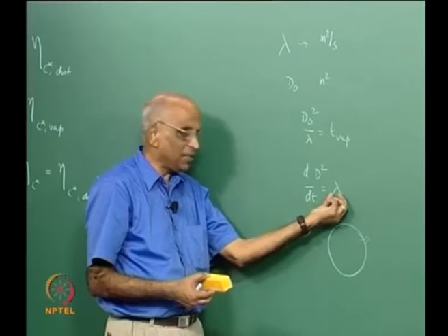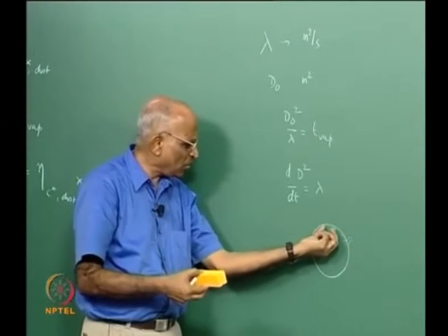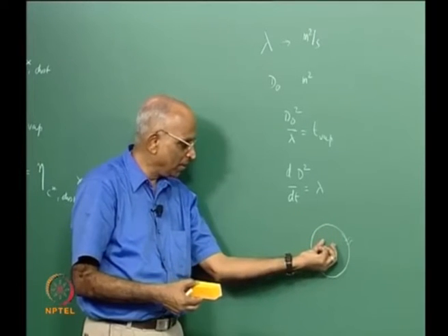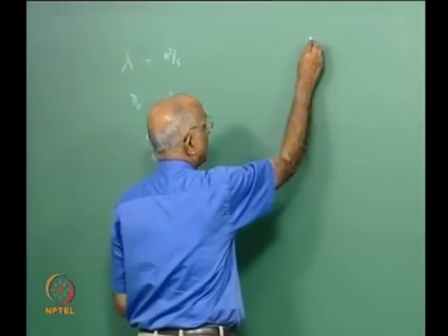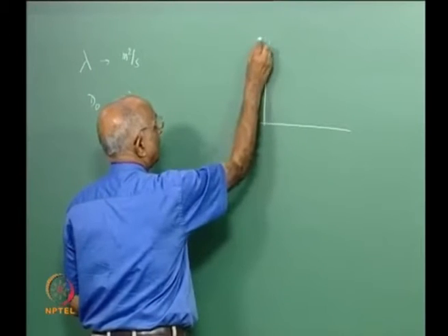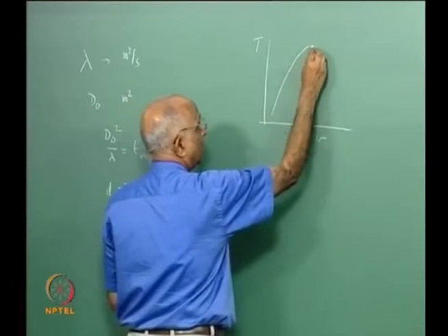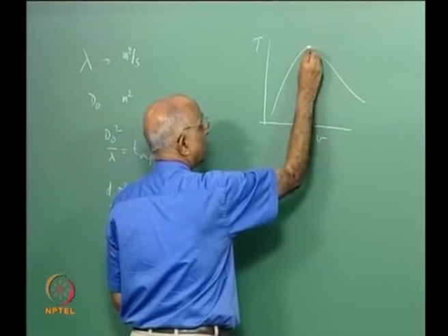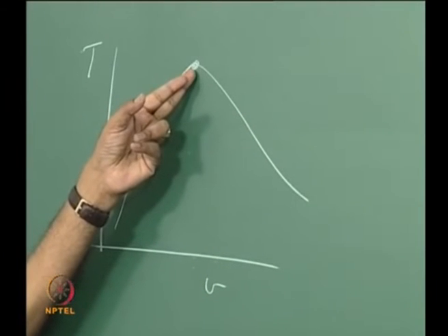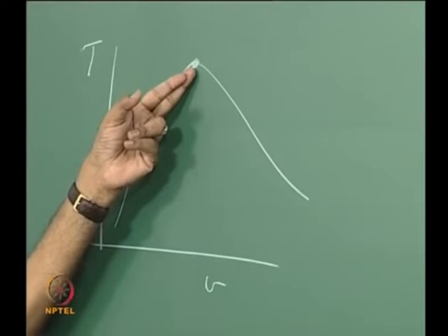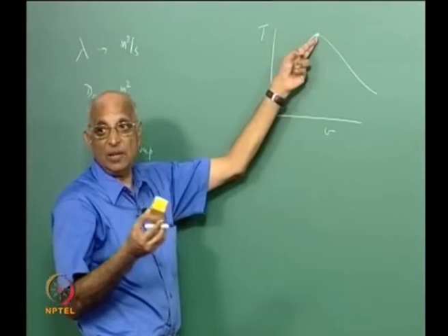We found that lambda decreases at high pressures, but again it picks up at very high pressures, and we also find that at high pressures a droplet may become equal to a gas. In other words, if I were to plot something like a phase diagram, maybe a T and V diagram, I have the solid line, I have this line which is a liquid line, I have the vaporization line, this is my critical point. When I approach the critical point, and this critical point is not very high, for kerosene in oxygen it could be as low as 50 bar, but I operate my chamber pressure at very high pressures.